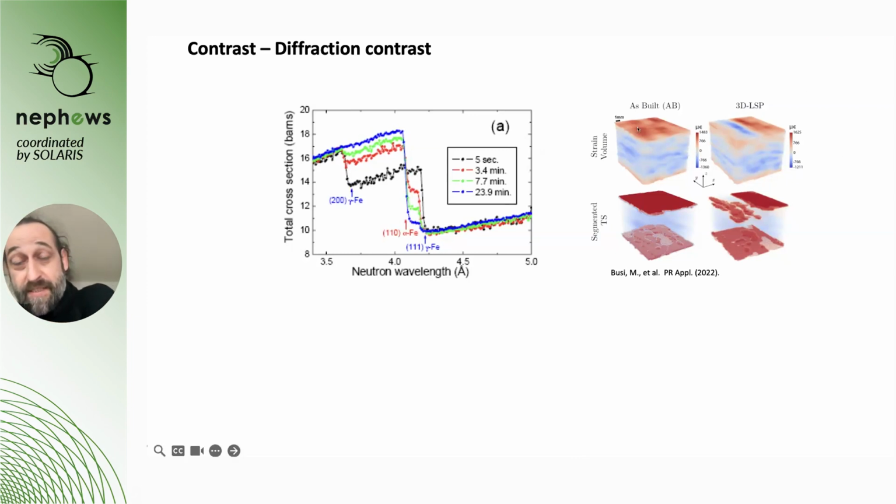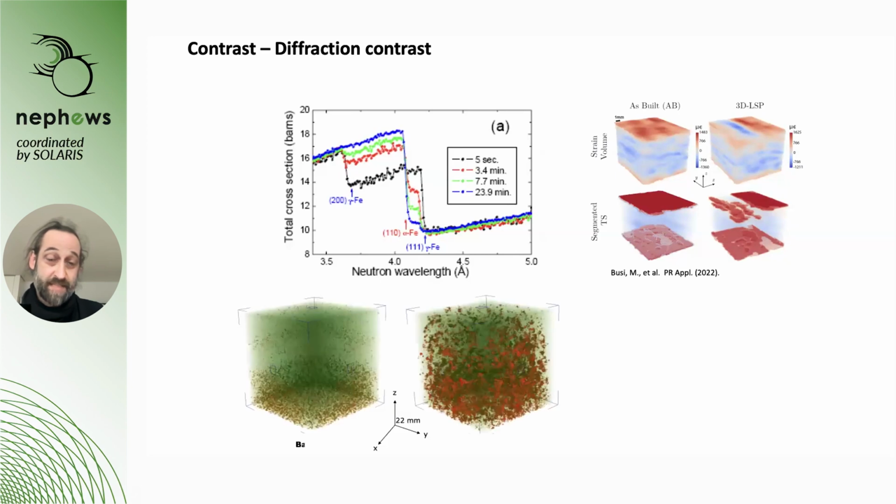And what one wants to avoid is these high tensile stresses on the surface, because that leads to failure of the material under fatigue. And so we have laser shock peened half of this sample on the surface, and we see how we can turn the tensile stresses in red to compressive stresses in the surface. And that, of course, helps the fatigue resistance of the material, and we can nicely control this with such measurements.